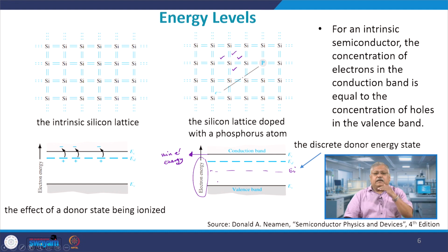Therefore the edge of the conduction band is the most stable part of any semiconductor for a free electron. Why? Because the energies are minimum. When the energy is minimum, that is where the electron will like to sit, right. But as you give more and more energy, let us say through optical domain or through biases, the electron energy will go high and the electron will be shifted higher and higher in the conduction band. And when you remove the energy, they will dissipate the energy to the lattice and come back again to the edge of the conduction band. This is what we have learned.